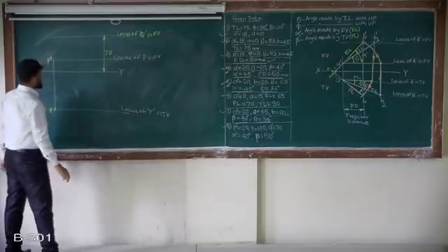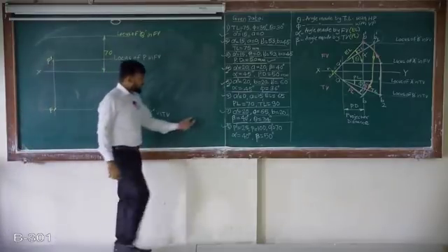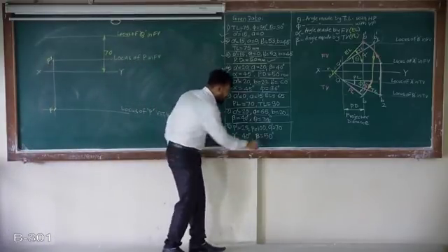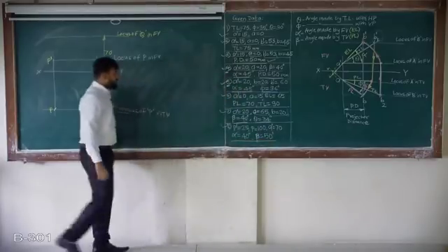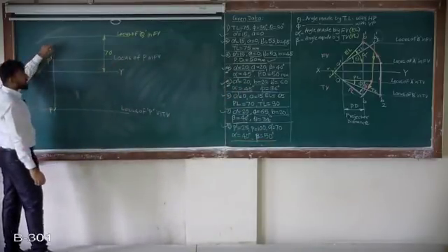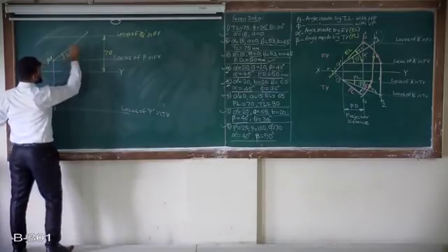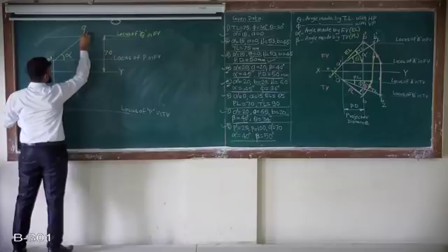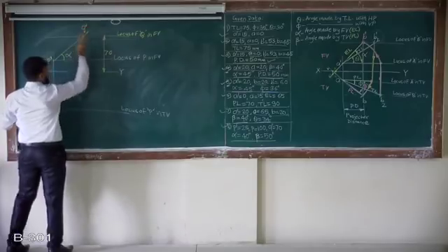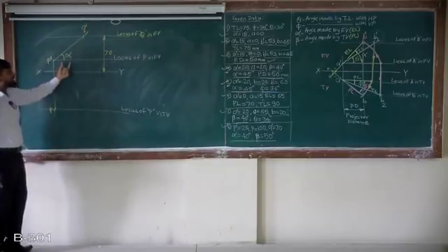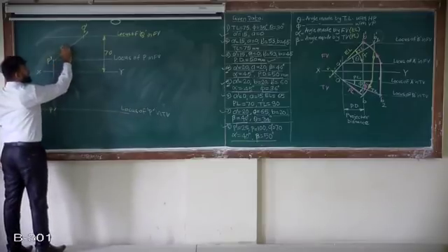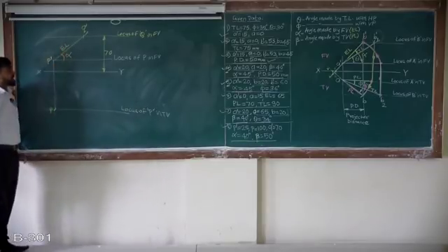So that is 70 mm. Next, I know alpha and beta, these two angles. I know point P dash, I know Q locus, so I will mark here angle, that is alpha. So this point will be point Q dash, because angle is apparent angle, corresponding length is elevation length.